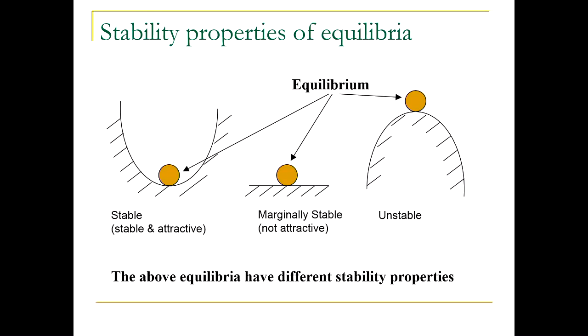In a cruise control example, you set the desired speed. If the car is unable to maintain that speed, under some disturbances like a slope up the mountain, well, that equilibrium is not stable then, right? So we inherently want to design systems that converge to some steady state operating regime most of the time. In many cases, that's the case.